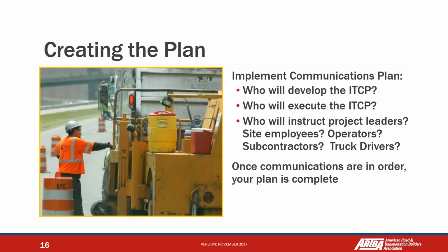So also we need to think about who will develop the internal traffic control plan. Usually the foreman is going to do the drawing. Who will execute the internal traffic control plan? Also the foreman, but we can also ask the supervisor to supervise and do some inspections regularly, talking with the workers about whether the plan is working, whether they are implementing and following the plan, and so on.